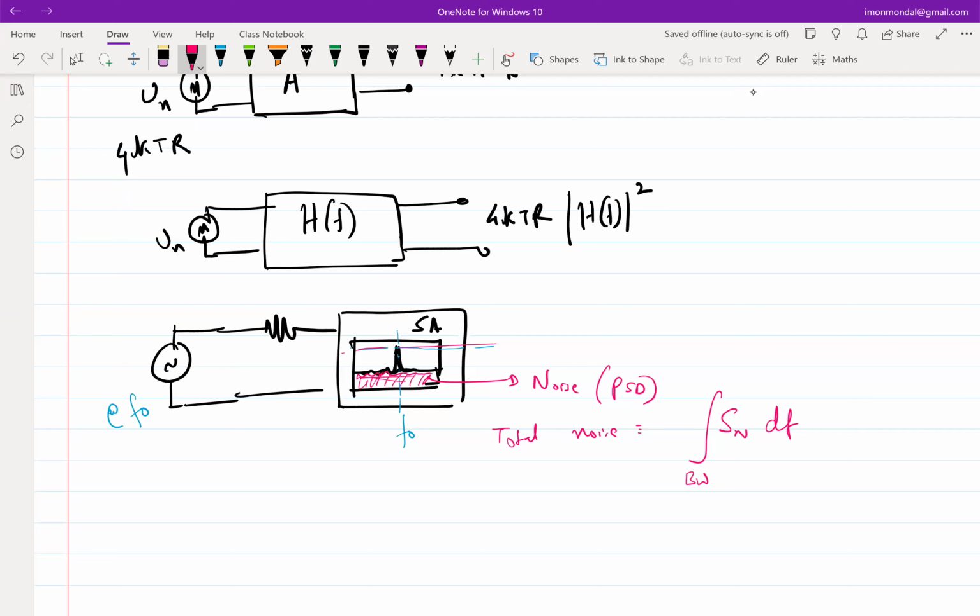You can do that. Alternatively, satellites are also power sensitive, in the sense that you do not want to spend too much power transmitting signals from a satellite. The moment you say I want to send more power, the power efficiency goes for a toss. Alternatively, whatever I am able to send, I will send in that limited bandwidth. At the base station, I will put a very sharp filter within that 1 kilohertz only. I will not have any redundancy, and my signal to noise ratio will be decent, right?